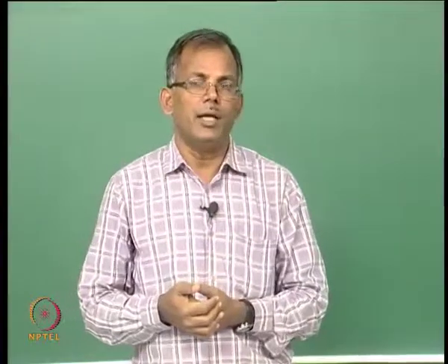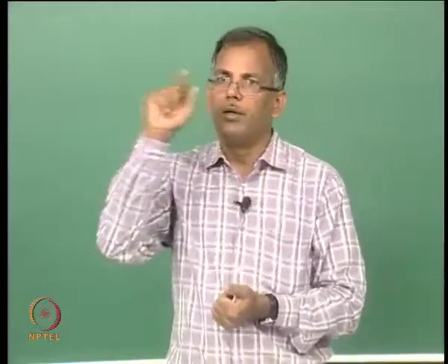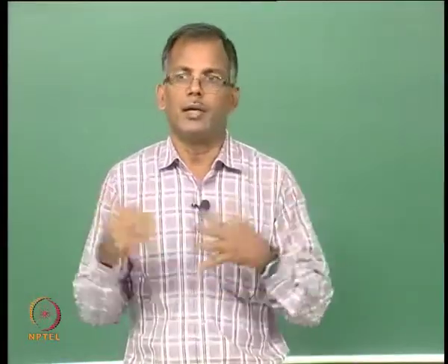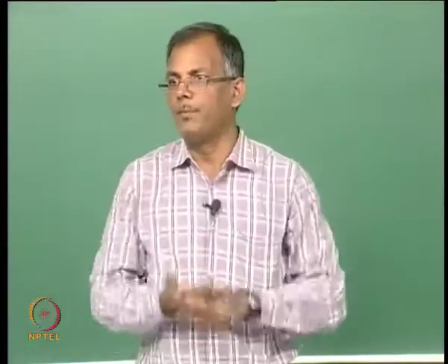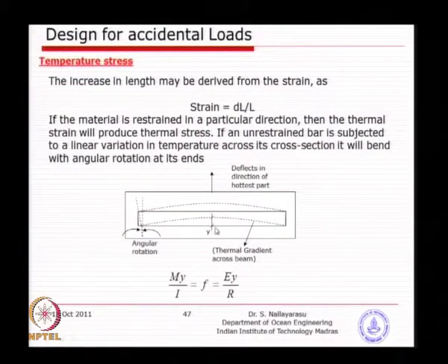So, you can see one important thing: when the beam is bending, one of the surfaces is going to get a compressive force, the other surface is going to get the tensile force. So, this shrinkage is also a problem depending on the type of cross section. If the shrinkage is too large, buckling may initiate, and that is where most of the failures due to fire happen, because of this large deformation.